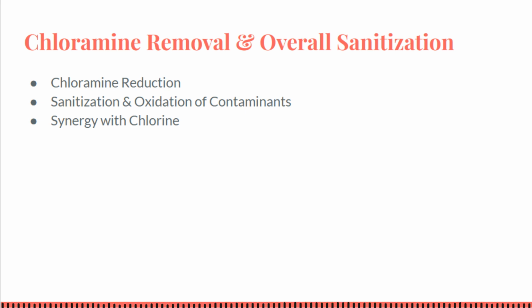AOP systems go even further. The hydroxyl radicals generated are even stronger oxidizers, virtually ensuring any chloramines that pass through the system are destroyed. In fact, AOP is noted to prevent chloramine formation and eliminate the associated odors and irritations, dramatically improving water clarity and comfort.